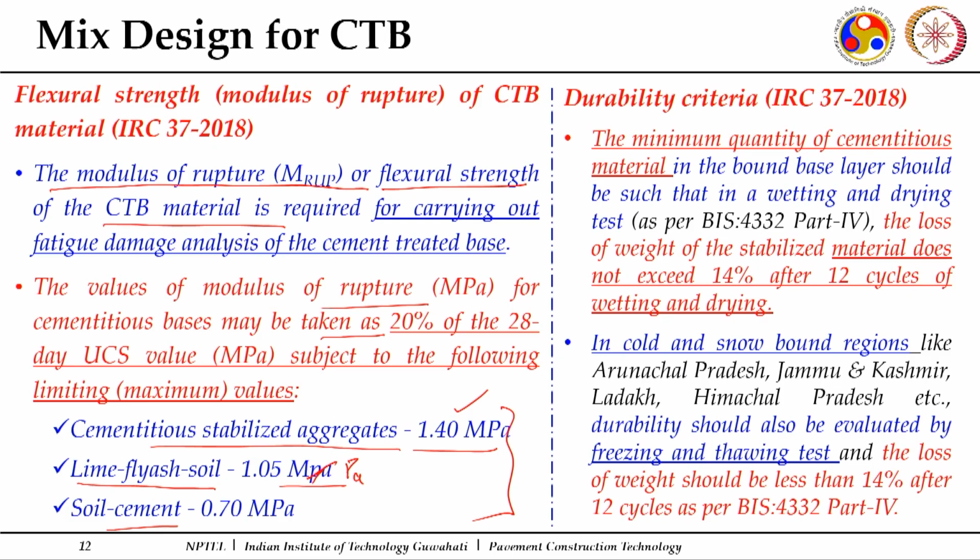In addition, when cement treated base courses are used, so as to avoid any reflection or propagation of cracks from these cement treated base courses to your bituminous courses, a crack relief layer is also provided.